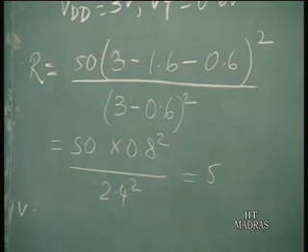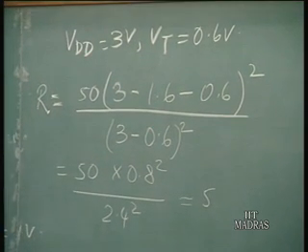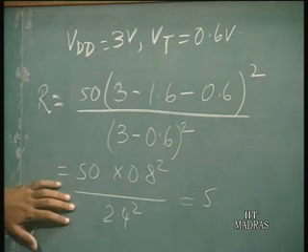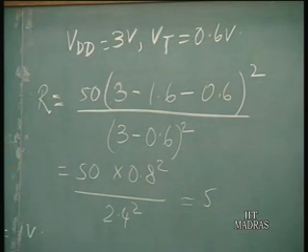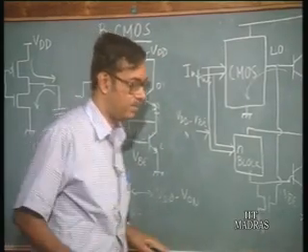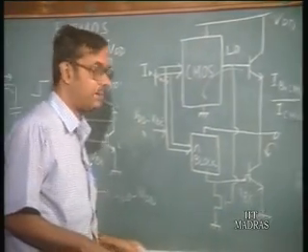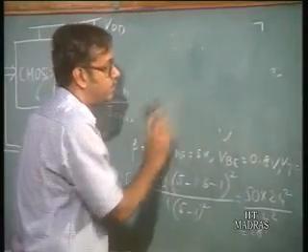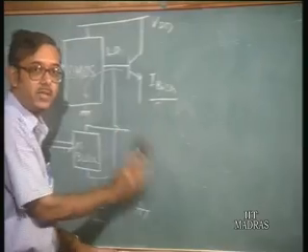Okay. So, this ratio is further reduced. So, we see that as we go for lower and lower voltage circuits, this ratio is reduced. So, the advantage of BiCMOS is severely reduced as we go for lower and lower voltage circuits. So, if we go for say 2.5 volt circuits for example, then the BiCMOS would not be as advantageous as a CMOS. So, there have been a lot of circuits which have come up, which would like to retain the advantages of BiCMOS even at low voltages.